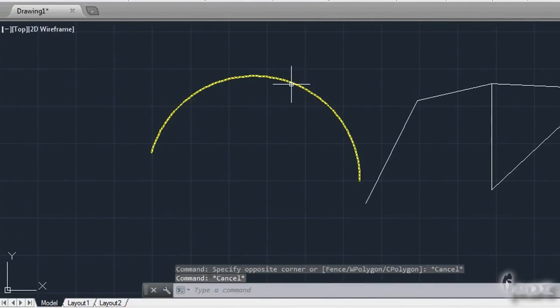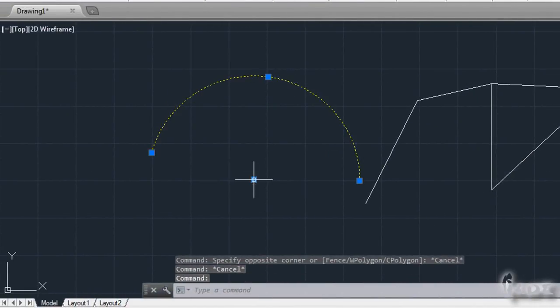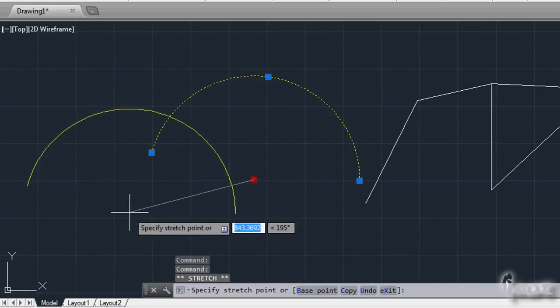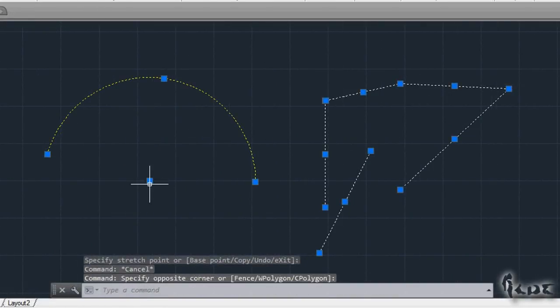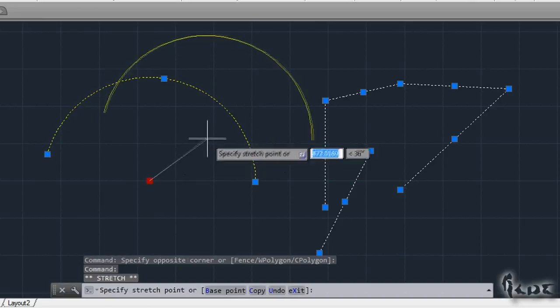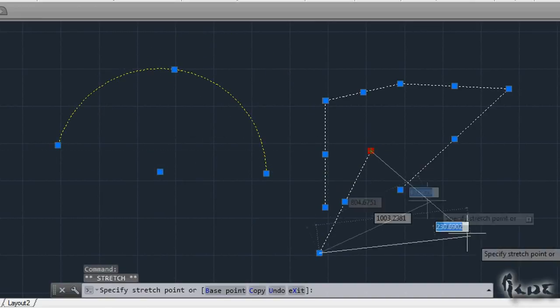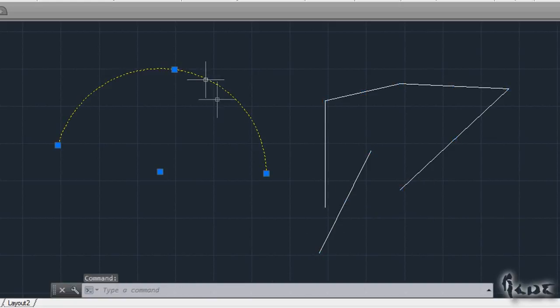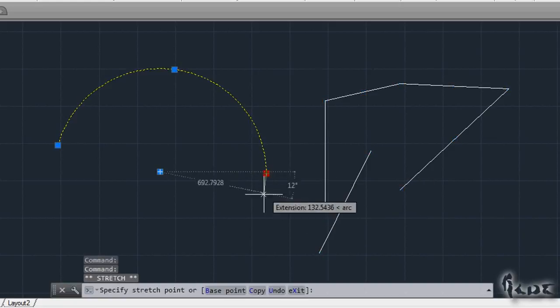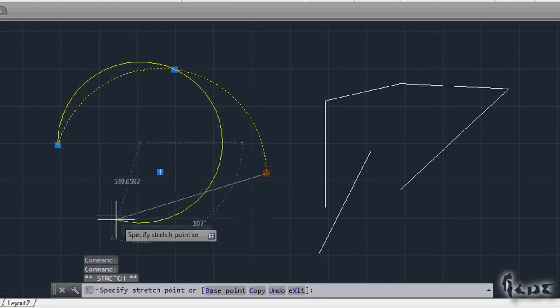To move an object singularly, select it first and click on the point in the center. This is valid even if you have more objects selected at the same time. Whereas to edit an object, you can click on its basic points that you used previously to draw the object itself and move them to go on editing.